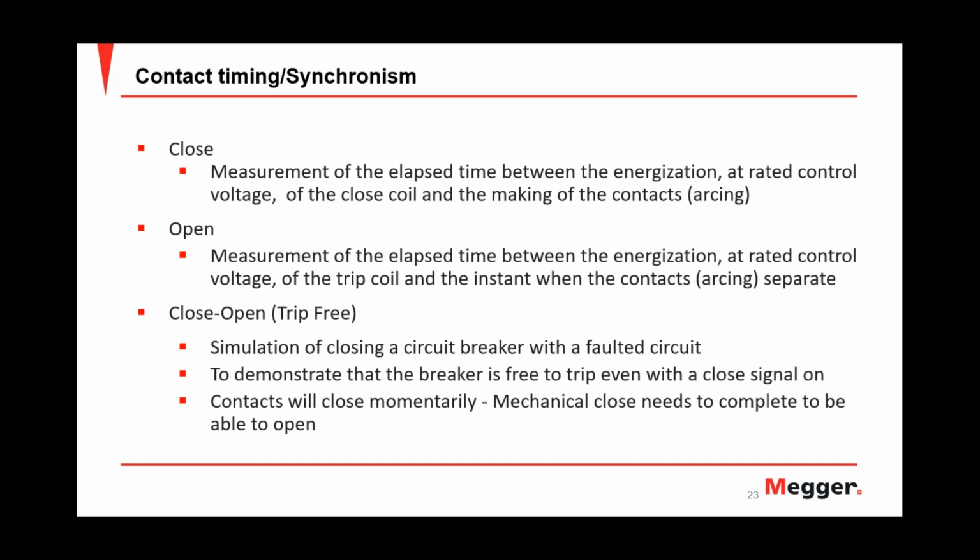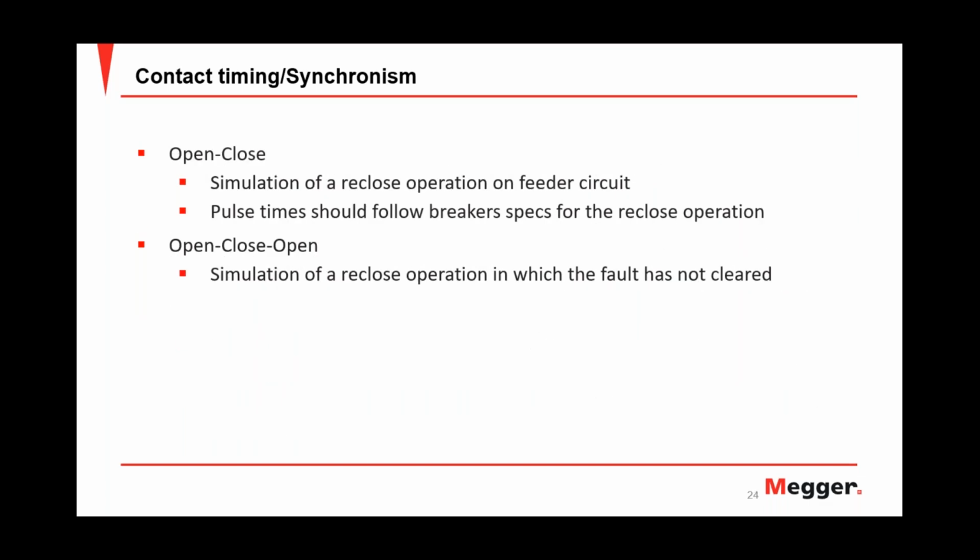The contacts will be closed for a very short time, and the mechanical part of the circuit breaker needs to be completed to be able to open. An open-close operation needs to be performed to simulate a reclose operation on feeder circuits. One of the challenges is for the pulse times to follow breaker specifications for the reclose operation.